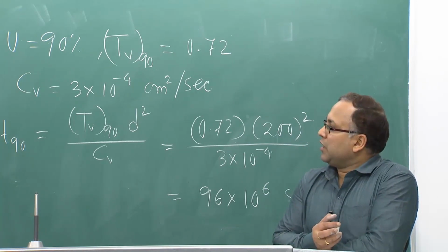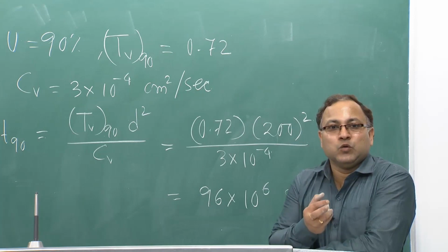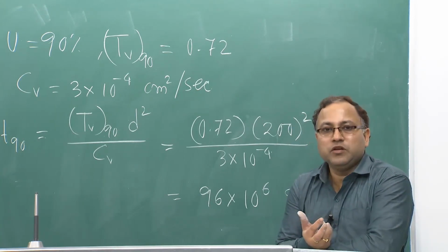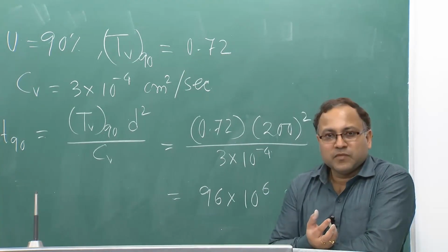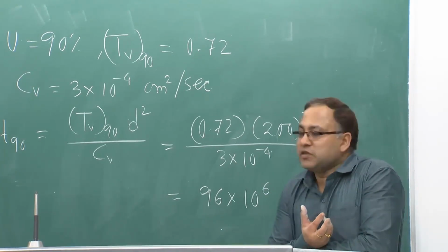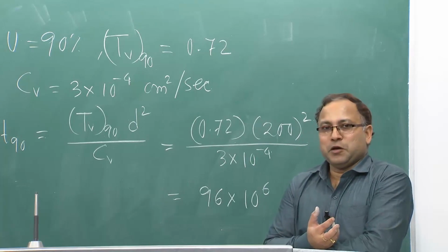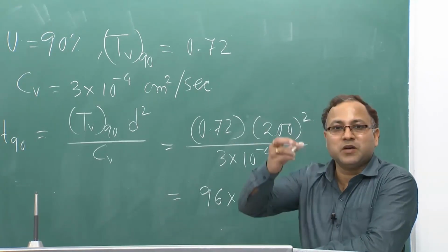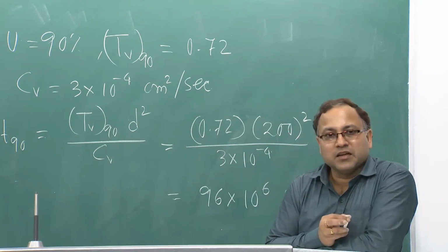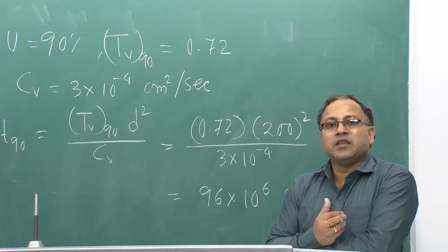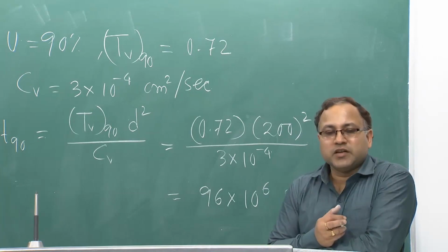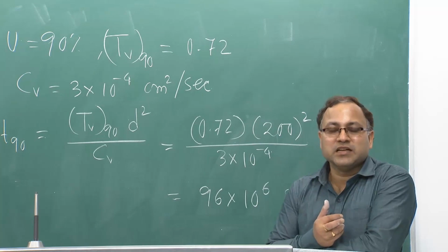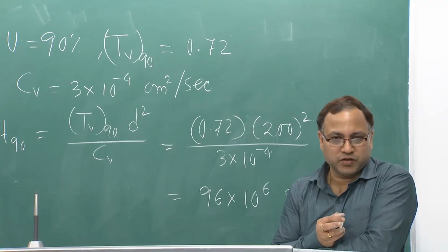This is quite a huge time, right, as far as any project is concerned. If you construct a structure on this kind of deposit, and that structure gives 40 kilonewton per meter square additional pressure at the middle of the clay layer, that will cause consolidation, and it will take almost 3 years for 90% degree of consolidation.